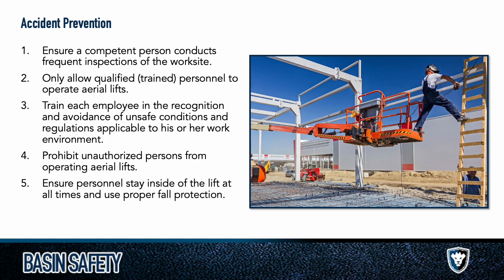So we want to make sure that a competent person is inspecting not just the equipment, but also the work site. These things are designed to be level and flat, and a lot of them are used in non-level areas, such as work sites and pads and locations, and even out in the back in the yard. And so we want to make sure that it's good conditions. When people get hurt on aerial lifts, typically it's because of the work site location. There are issues with it that aren't accounted for. People are trying to get stuff done, and they move forward without thinking through the worst case scenario.